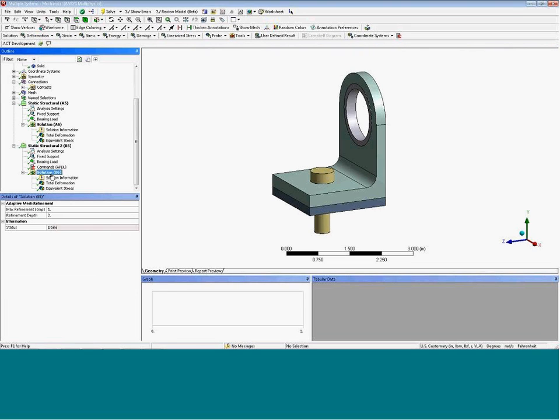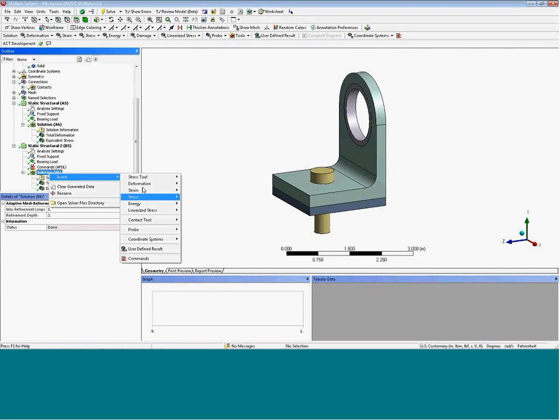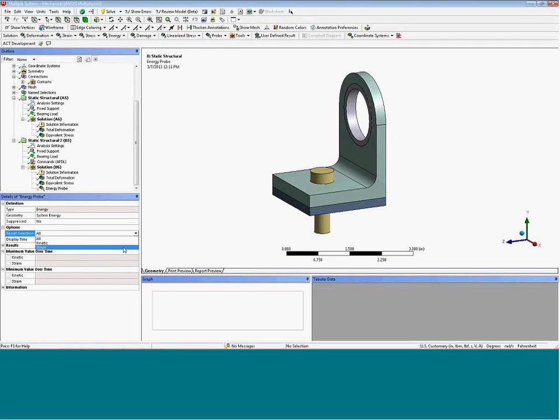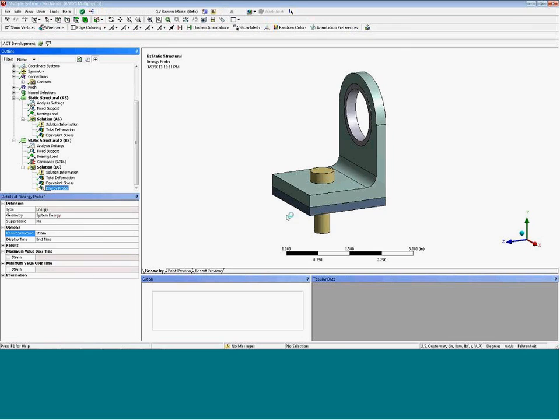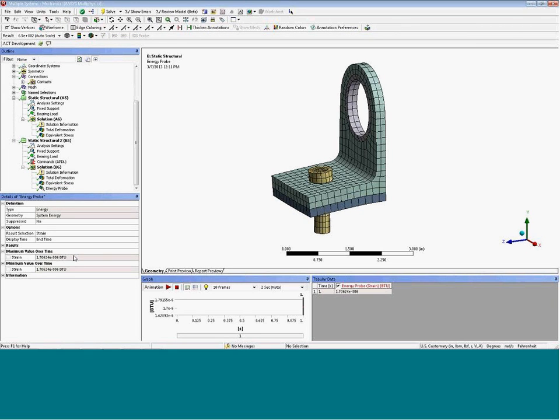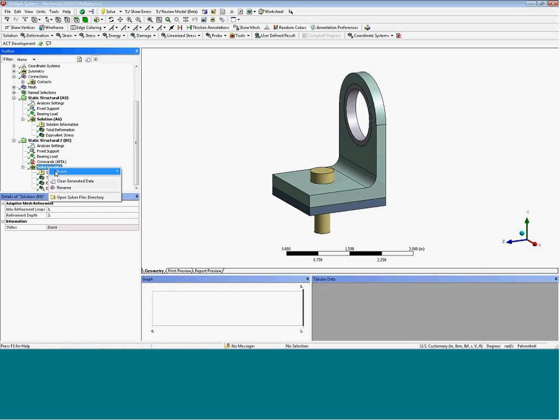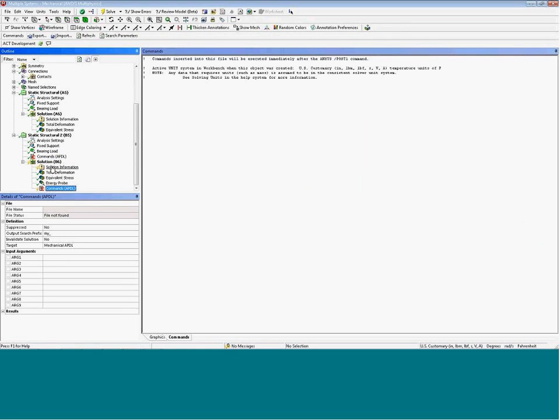Another example of this is also in post-processing. If I insert, say, this energy for the body or a thing in the model, this shows up as 1 to the -6 BTUs. So I could get this information through a command block, and this is the first post-processing command block we've seen, where files here are executed just after POST1. We're in the general postprocessor in classic ANSYS.